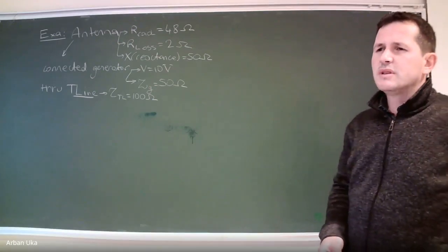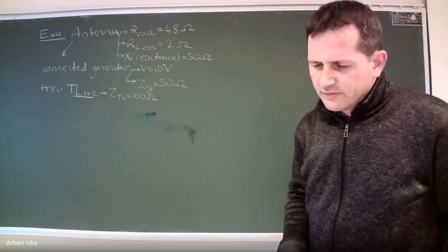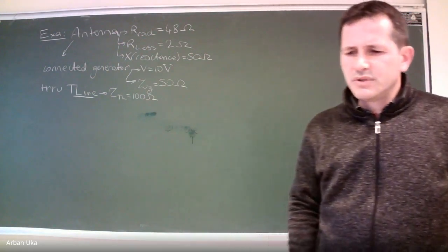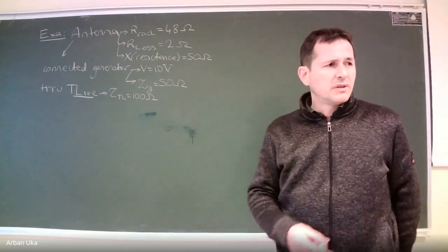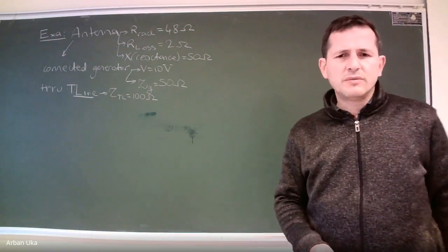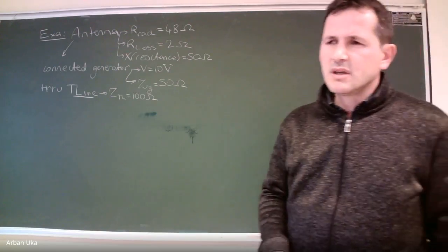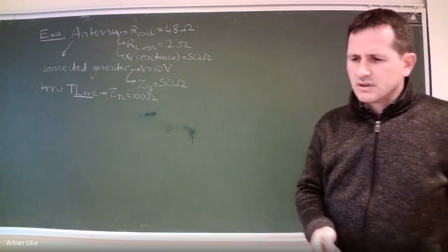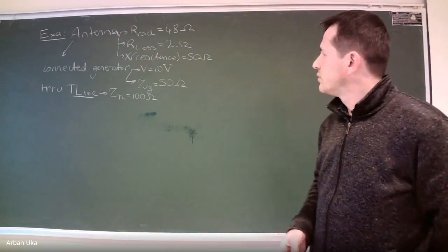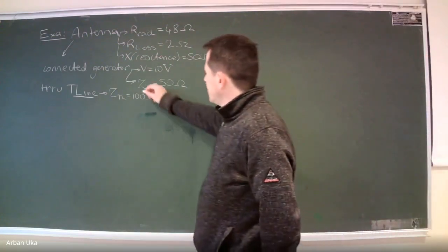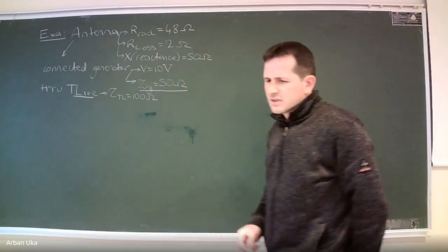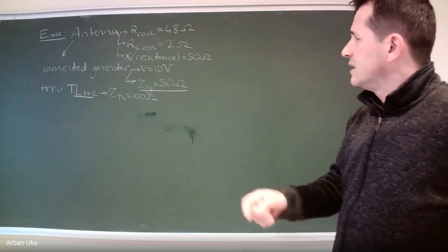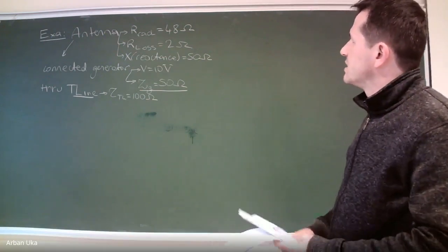Also, many multimeters or oscilloscopes that you can find here in the lab have two settings of the internal impedance. It might depend on the product, but sometimes they have a 50 ohm and sometimes a 1 megaohm impedance for the input signals. So whenever you are reading a voltage on a digital oscilloscope, you may have to switch, or at least test the two possible different impedances by selecting it. Now let's see the problem again.